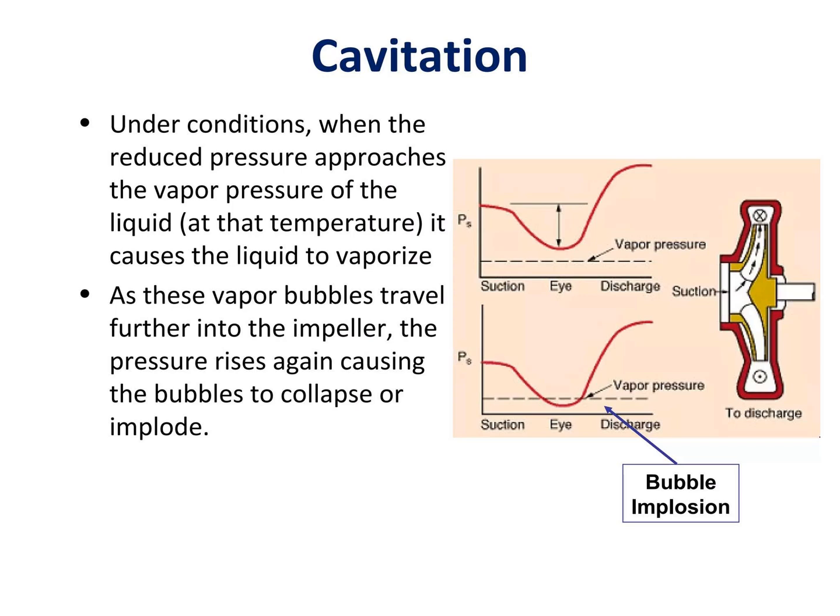When the liquid reaches the area with low pressure, and if the pressure becomes equal to the vapor pressure of the liquid, that liquid will vaporize. That's how vapor forms inside the pump. This vapor is present in the form of bubbles. When these bubbles go to the high pressure area of the pump, bubble implosion takes place that forms micro jets that collide with the casing and internals of the pump.